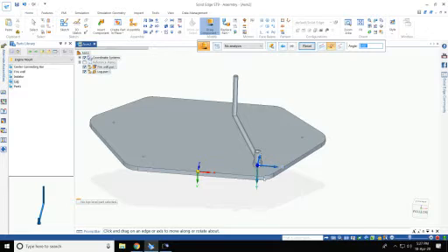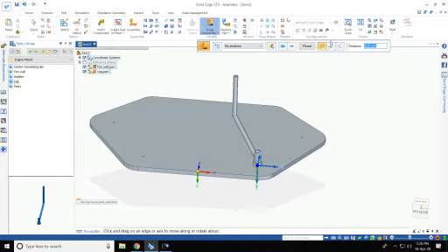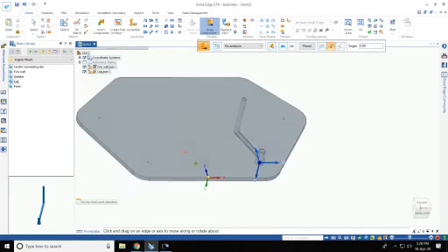To make this rotation enabled, here you've got how you want to use the drag component. I've clicked on rotation, so therefore I'm able to rotate it. If I wanted to slide it, I'd click on slide, but I can't slide it because the other 2 degrees of freedom are fixed. So it is mostly rotation. Done. Now take your second lug.